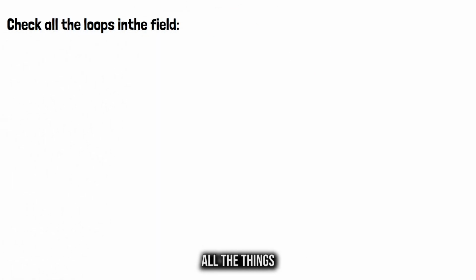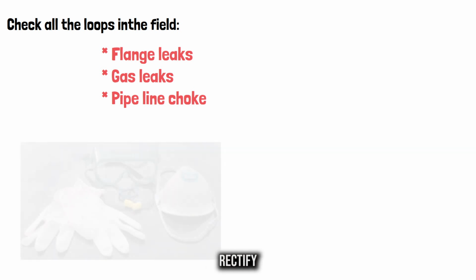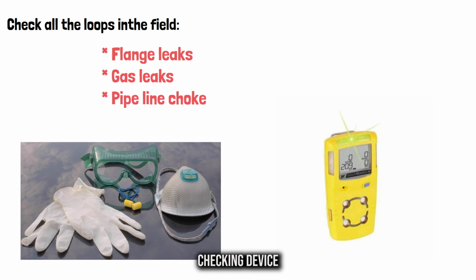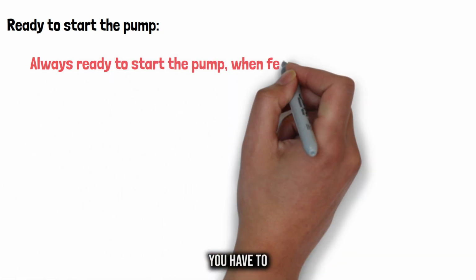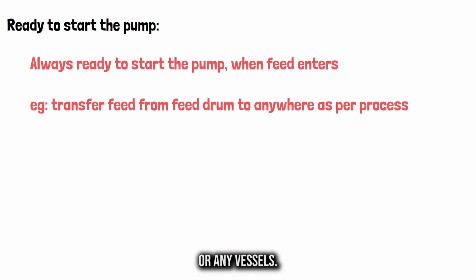4. Check the whole loop and monitor all the things, like flange leaks, gas leaks, and choke. Rectify if it happens using workers by giving proper PPE. And always take the LEL checking device with you. 5. Be ready to start the pumps, because once feed comes, you have to start the pump from the feed drum to the heater or any vessels.